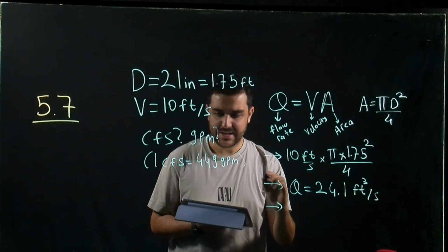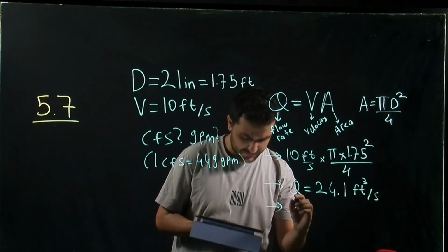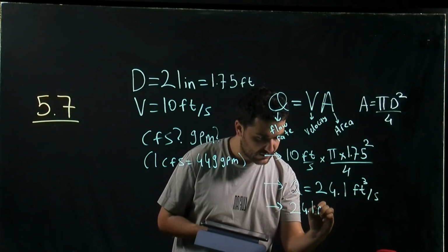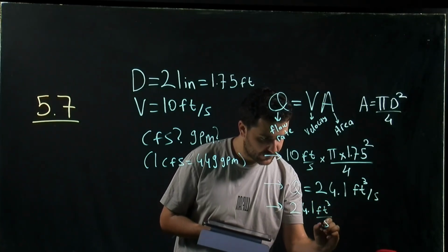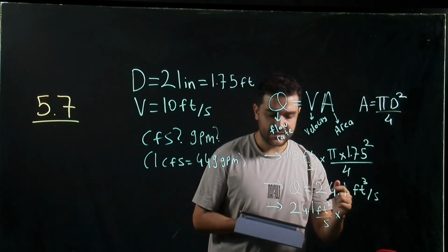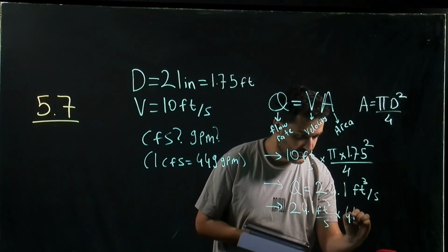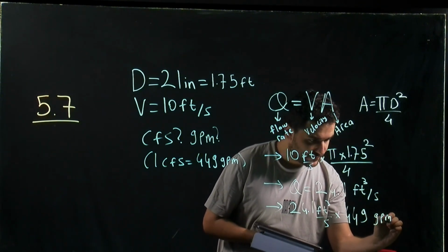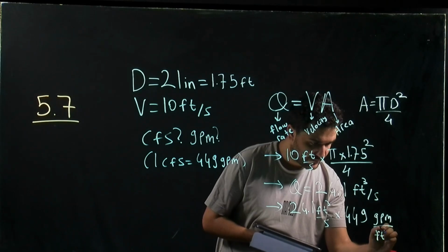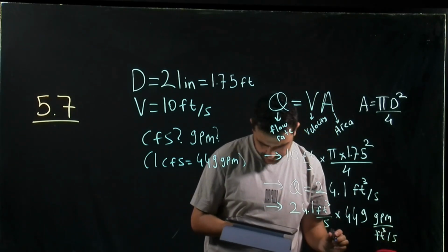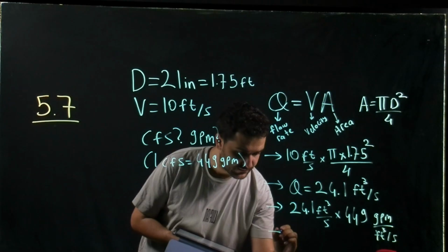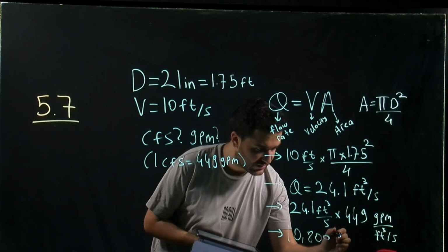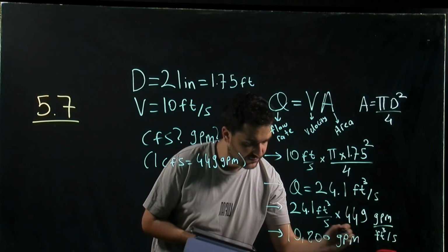Since the question also asks for GPM, we can directly multiply it by 449, and it gives 10,800 GPM.